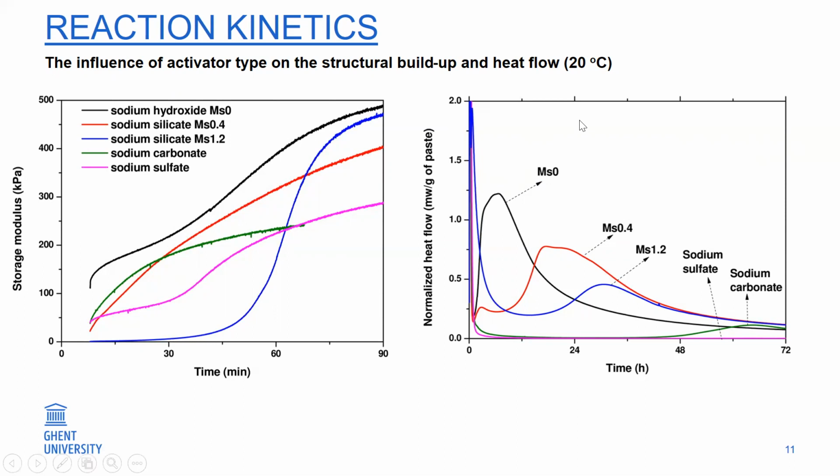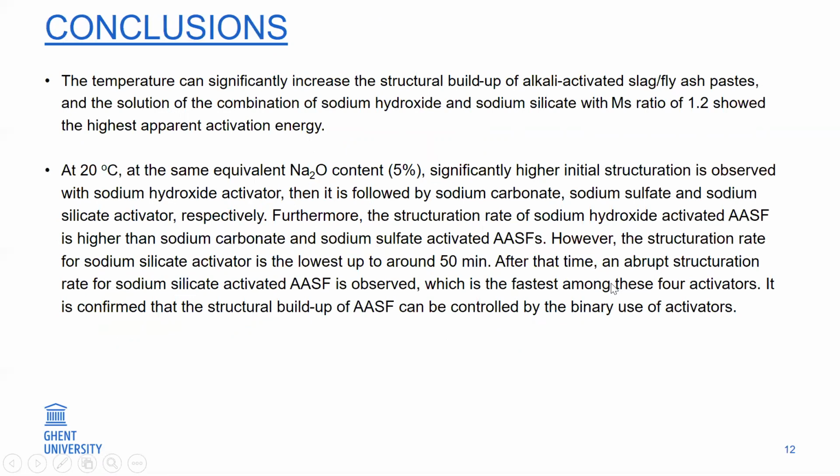And the right-hand side is the heat flow of these 5 different activator solutions. For the peak of the heat evolution, we can see the MS0 mixture shows the earliest acceleration period compared to other mixtures. And for the sodium sulfate, there is no acceleration period for these mixtures. That's also confirmed by previous studies.